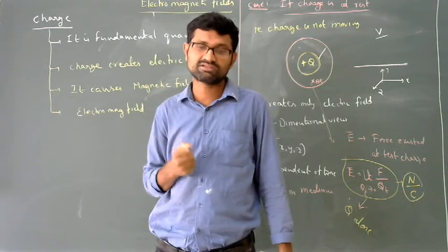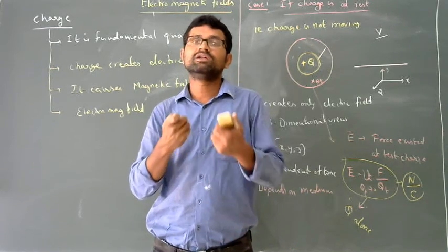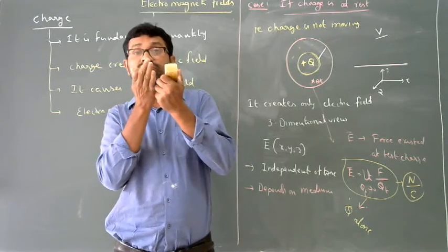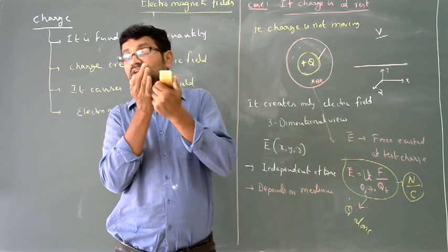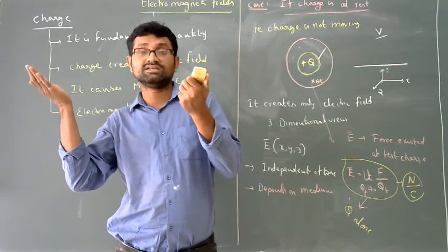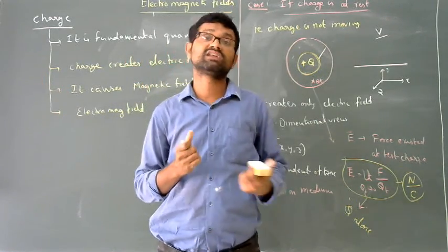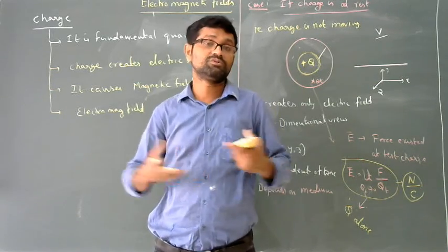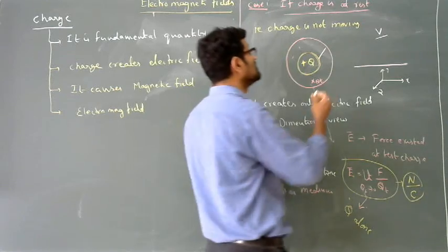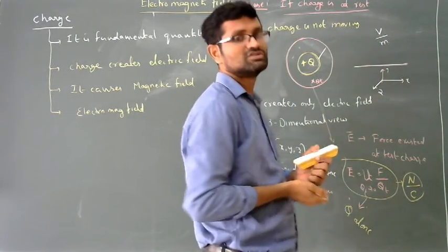Generally it is measured in meters, millimeters, centimeters, not kilometers. That depends on the voltage rating of a transmission line: between the conductor and any other conducting material, we provide certain spacing. If voltage increases, we increase the spacing, because the electric field intensity extends up to a certain distance around the conductor. So electric field intensity can also be expressed in volts per meter.